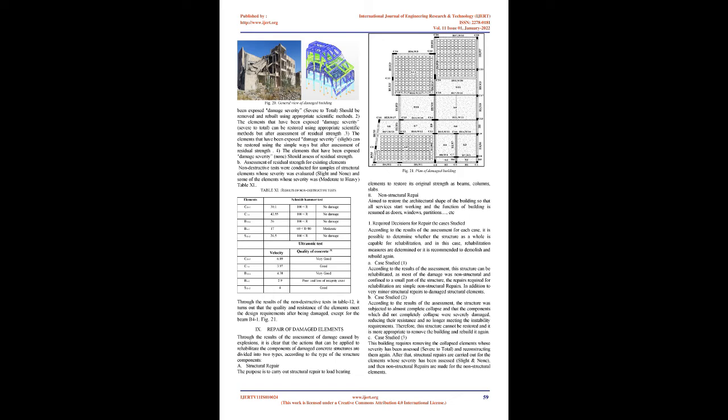A. Determine the force-resistant paths. Adopted computer modeling, Robot, by applying a complete simulation of the building after the occurrence of damage, and applying the loads on it during the occurrence of damage. The building has been modeled according to structural drawings after documents review and verification of as-built construction. Removing the columns that were severely damaged, from severe to total, and applying the loads present during the explosion, Fig 20.